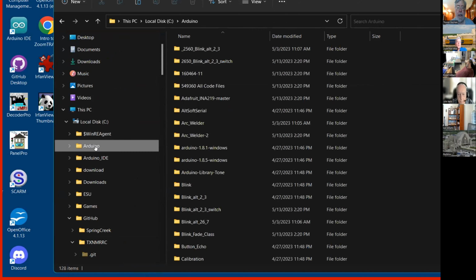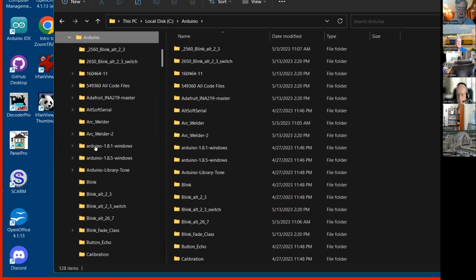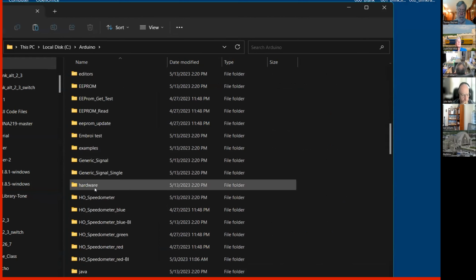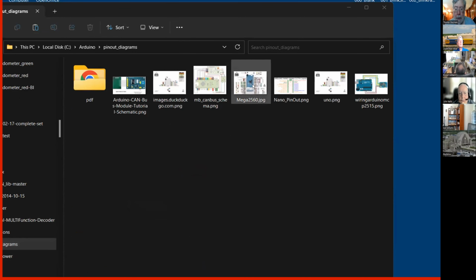But there are several different doodads you can use to expand that. There are some things that are I2C. I happen to like the shift registers. A shift register takes, I think, 3 or 4 pins, depending on which flavor it is, and each of those shift registers will give you 8 pins, either input or output. So for digital pins with a shift register, pick a multiple of 8, and that uses 4 pins.